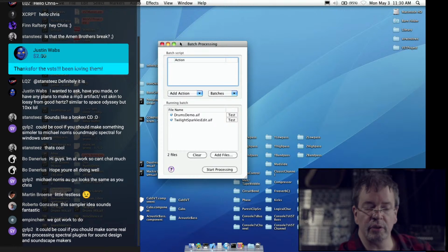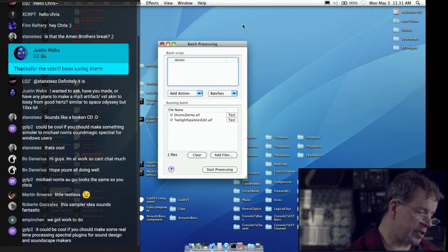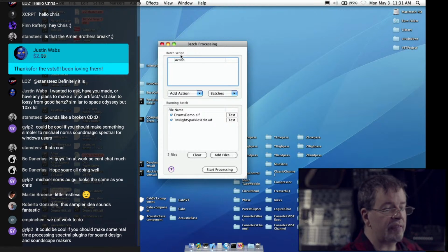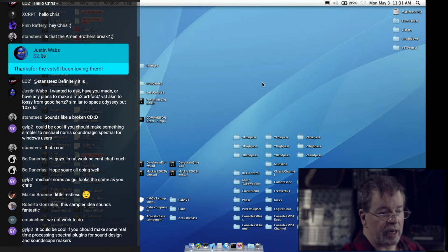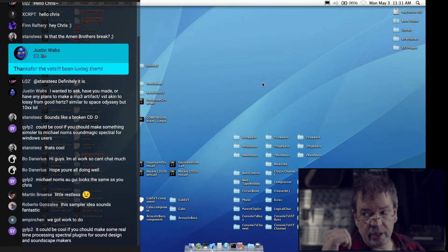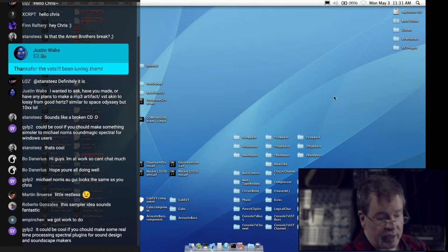And the additional stuff on that module, which you can build yourself, is actually quite affordable. But the additional stuff on the module is largely for buffering inputs and outputs and things. And if we're willing to consider it a sort of sacrificial Teensy, we don't necessarily have to do that. We could hook one up, power it up, program it by plugging it into the computer and telling it what to do, and then just take the output directly and run it to stuff. So it could serve as a little tiny sampler, because what we just heard was effectively a Teensy running as a little tiny sampler, and in fact being re-triggered as if it was a sampler. And it's weird and glitchy and terrible, but that can be fun too.